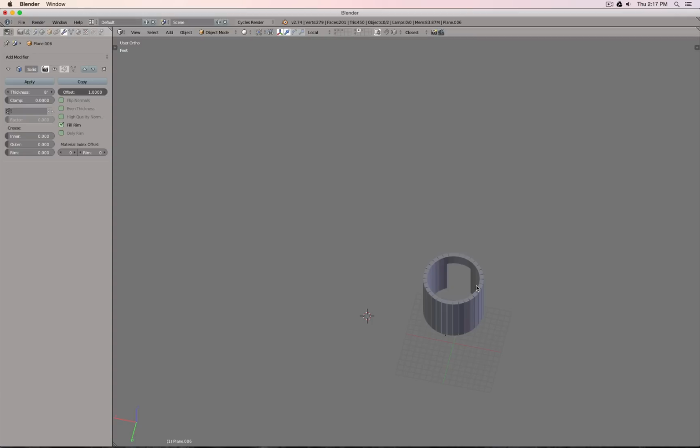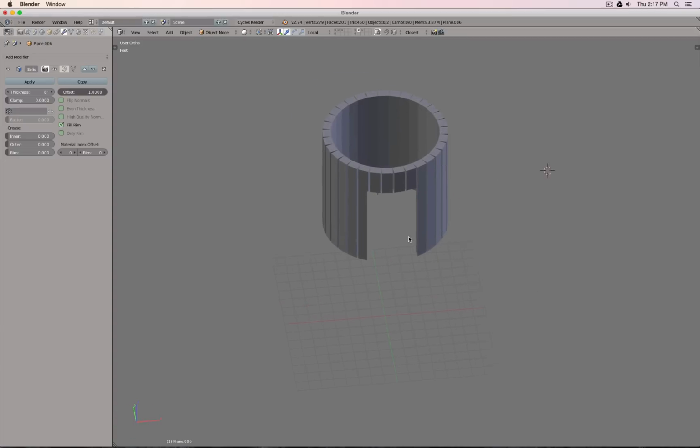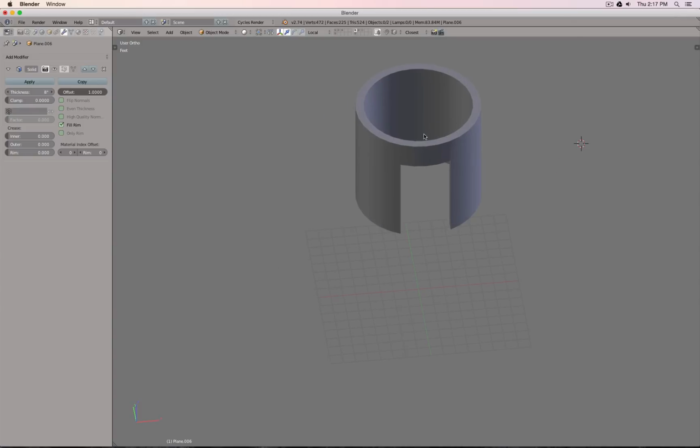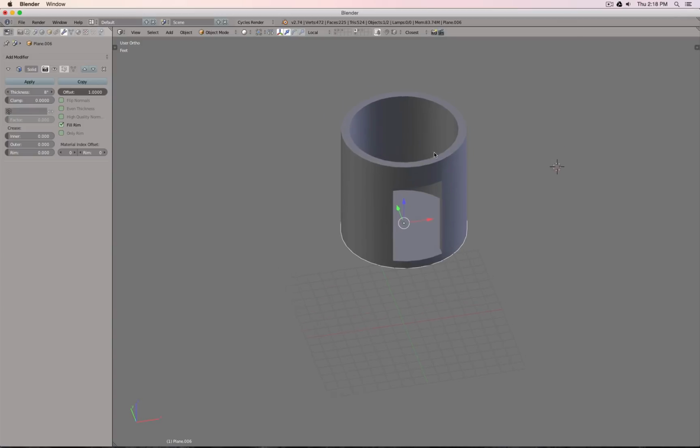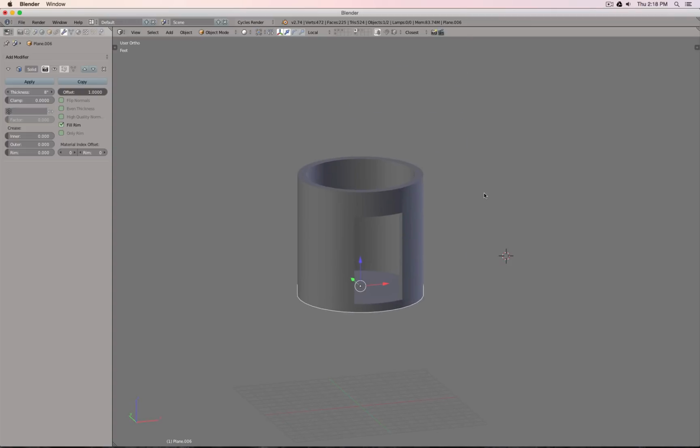If that template then works, then go ahead, make the drawing for the laser cutter, cut the foam core piece out, and then take an X-Acto knife, cut in all these grooves, and bend the piece into the shape. And in this way, recreating something like this out of foam core and a laser cutter is also not really a big problem.